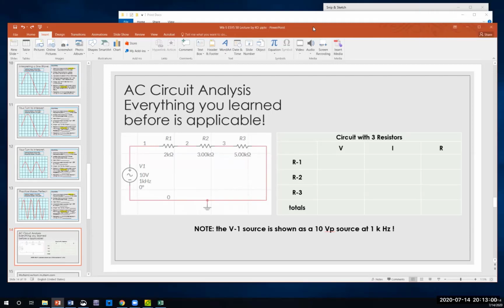Oh, okay. Sorry. All right. So you're used to working at warp 9, and I want to make sure I don't leave anybody behind. So before you fill in the entire current column, because if you found one current, you have found them all, what is the caution I asked everybody about at this point? Before you go filling in that column, you want to make sure that calculation is correct. Maybe you should recalculate current to make sure your current is good. So 10 volts divided by 10 kilo ohms, you just do that again, and you confirm 1 milliamp.